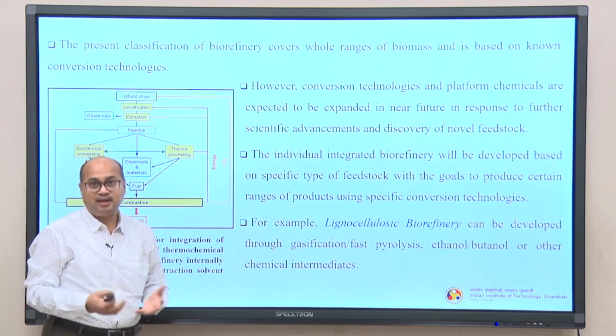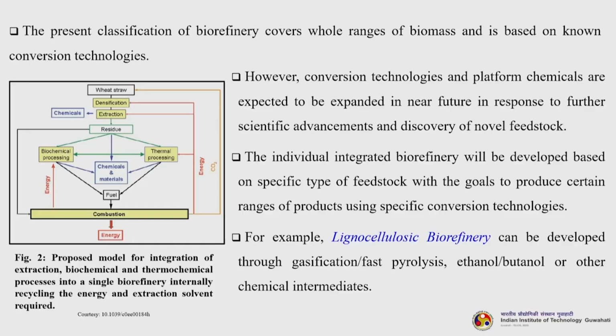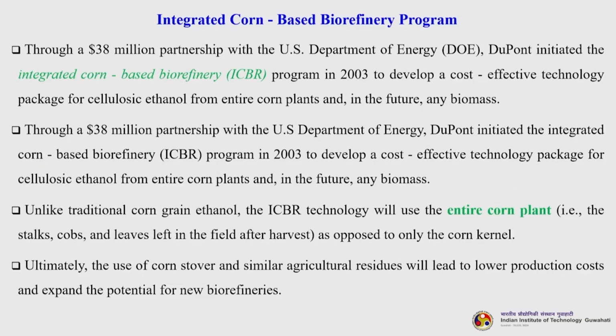environmental benign technology. However, conversion technologies and platform chemicals are expected to be expanded in the near future in response to further scientific advancements and discovery of novel feedstock. The individual integrated biorefinery will be developed based on a specific type of feedstock with the goal to produce certain ranges of products using specific conversion technologies. For example, a lignocellulosic biorefinery can be developed through gasification, fast pyrolysis, ethanol, butanol or other chemical intermediates. Now, we will discuss a few integrated biorefineries.